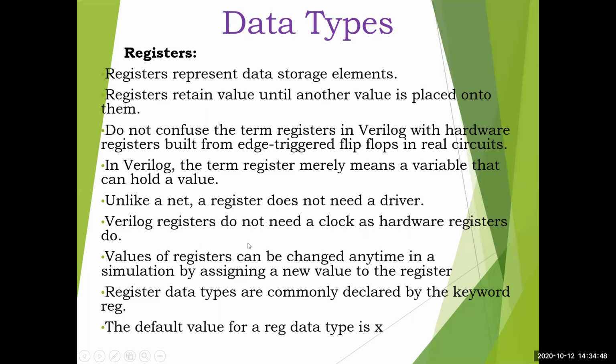Verilog registers do not need a clock as hardware registers do. It does not require any clock like in hardware circuits. The value of a register can be changed anytime in a simulation by assigning a new value to the register. So you can just change the value.